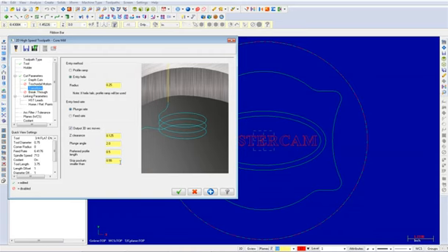Entry feed rate sets the rate that the tool feeds into the material. Output 3D Arc Moves is an option where Mastercam creates the helix with an arc of G2 or G3 moves. If this option is disabled, the helix will be created with many smaller linear moves. And finally, Z clearance is an extra height used in the ramping motion down from a top profile. It ensures that the tool has fully slowed down from the rapid speeds before touching the material.